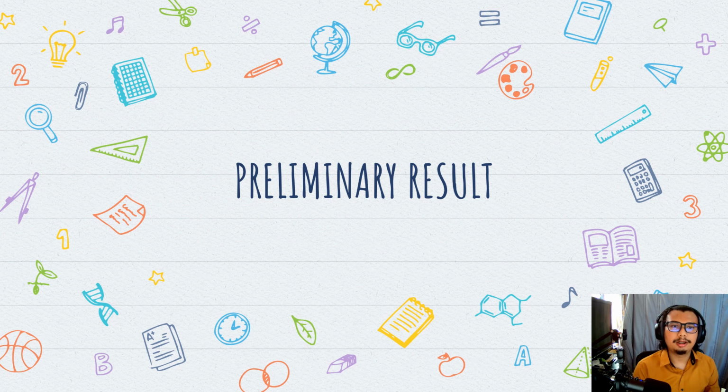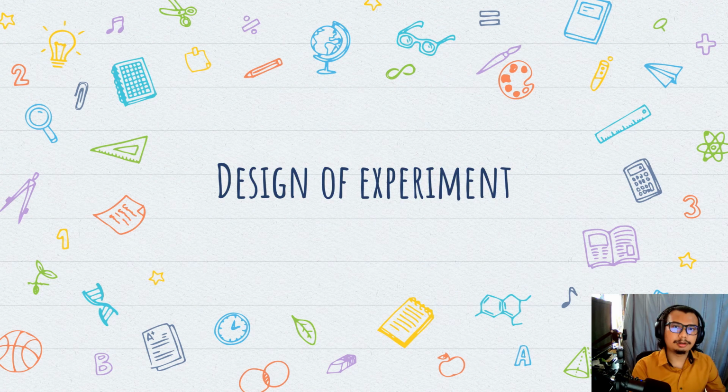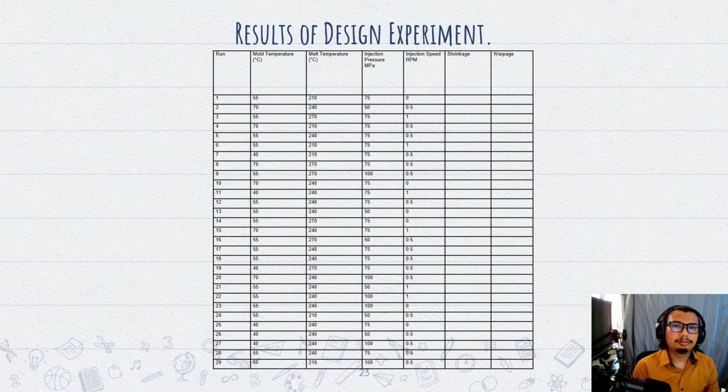Preliminary result. There are two results, which are the Design Expert DOE and the Moldex 3D simulation. Design of experiment. This is the result of the design of experiment by using Design Expert. As you can see, there are 29 runs based on the parameters that were chosen, which are mold temperature, melt temperature, injection pressure, and injection speed. The output responses we choose are shrinkage and warpage.